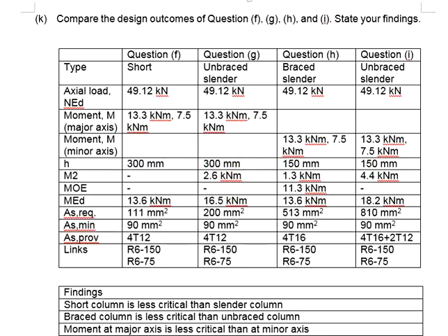In contrast, when the moment is acting in the minor axis, that means your h now will be the shorter width of the column. I guess by now, it shouldn't be confusing to you. There's only one principle to decide the h.